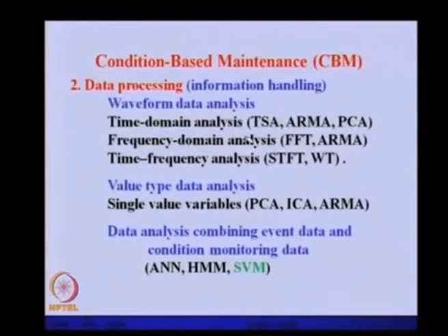Frequency domain analysis, FFT, ARMA model. These are auto regressive moving average models. These are all time domain and frequency domain models. Time frequency analysis, that is wavelet transform or short time Fourier transform. This kind of techniques are available to analyze the waveform data, such as in vibrations.